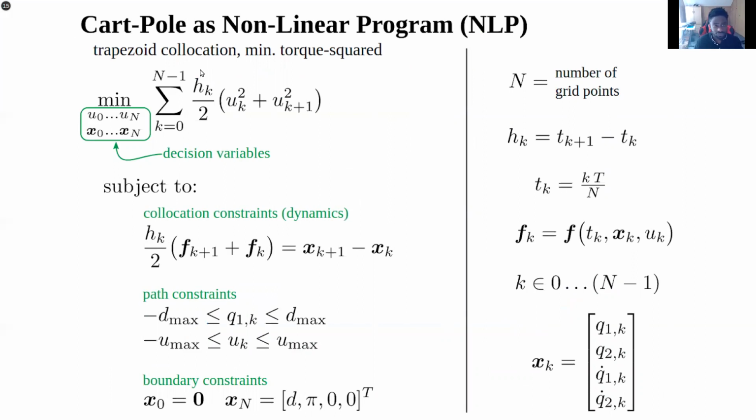We notice that instead of an integral, we now have a summation. It tells us that it's now a discrete time problem where we have discrete states and actions. It's subject to all of these discrete equality constraints, inequality constraints and boundary constraints. These are some descriptions of the state variables. And because we have inequality constraints, this ends up being a non-convex optimization problem.